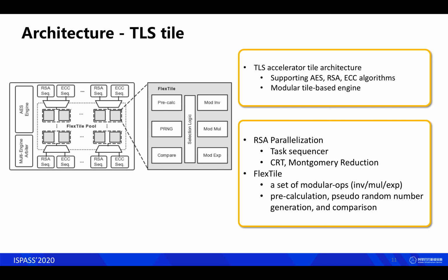CETUS employs a decoupled design paradigm that separates the basic operation modules from the control logic and wraps them in a tile that can be reused by the cipher algorithms. As can be seen in this slide, each tile contains a complete set of basic operation modules required to run these algorithms, including modular operators, pseudo-random number generation, and also comparison.